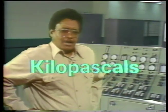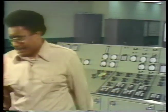So, if you know both the force exerted on a surface and the area of that surface, you can determine the pressure. The resulting pressure can be expressed in a variety of ways. One of the most common units for pressure is pounds per square inch, or PSI. In the metric system, pressure is usually expressed in kilopascals. Let's see how the formula and units are applied by looking at an example.